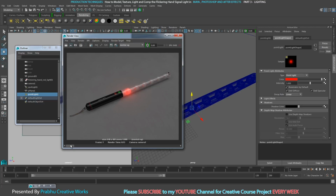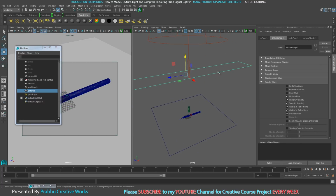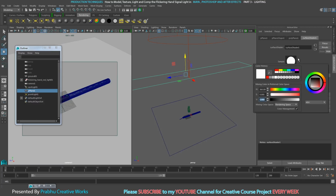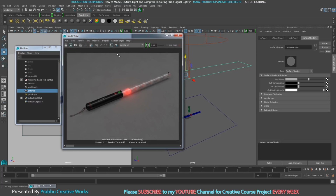See here it will increase my scene light high because it will happen by this plane. So select the plane, go to surface shader. So click this one, out color. Here we have HSV. So if you didn't get it, you want to enable over here. So hue saturation value, so I want to reduce this value to 0.3 or something, or 0.4, so that means your scene brightness will be reduced. So I will keep this image for my comparison and click render.